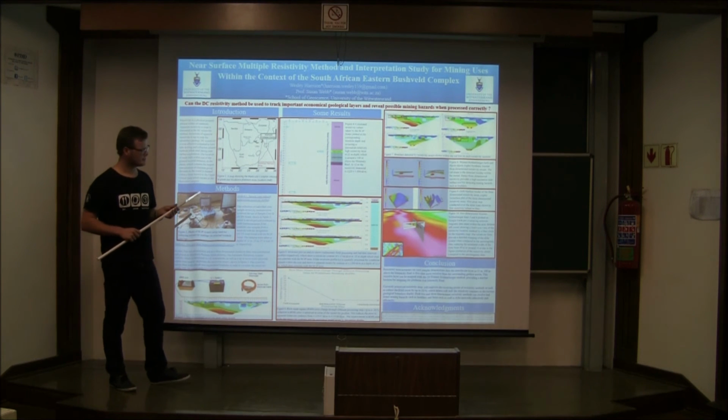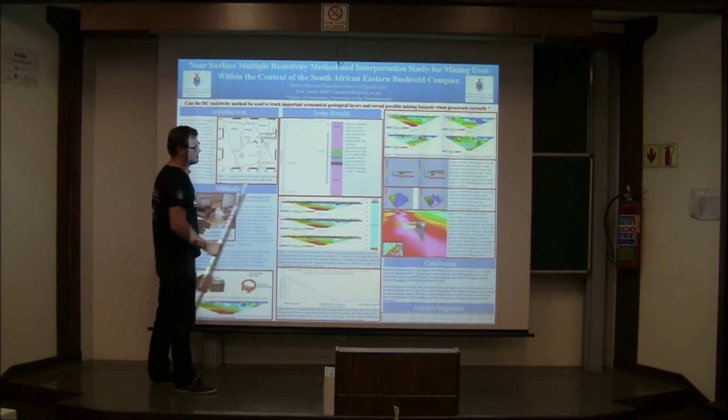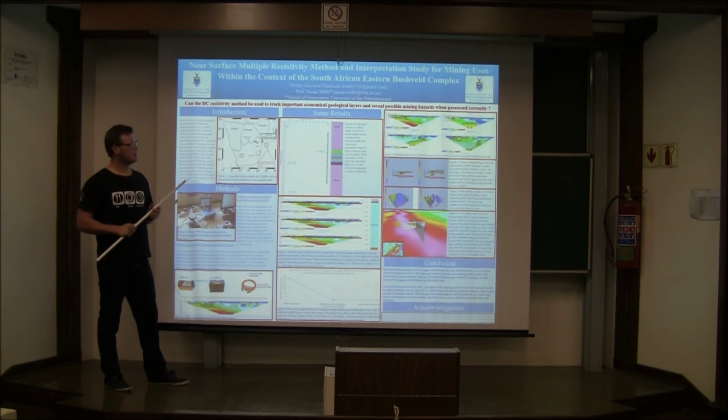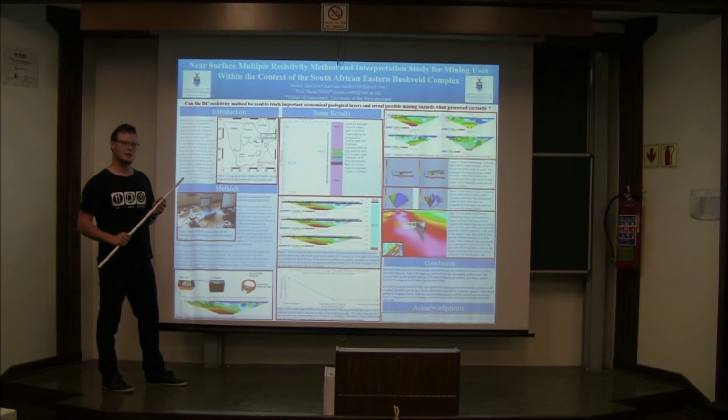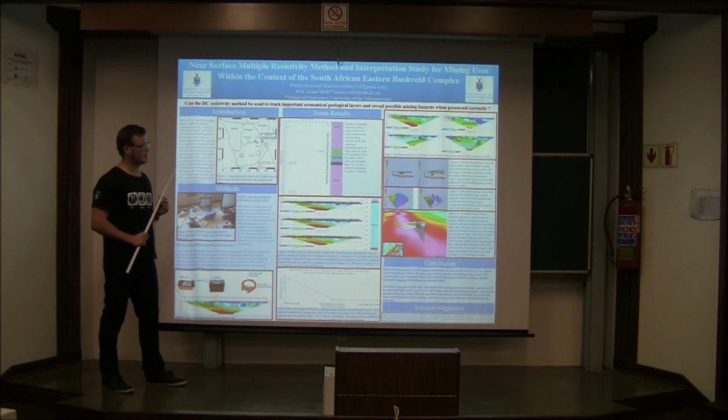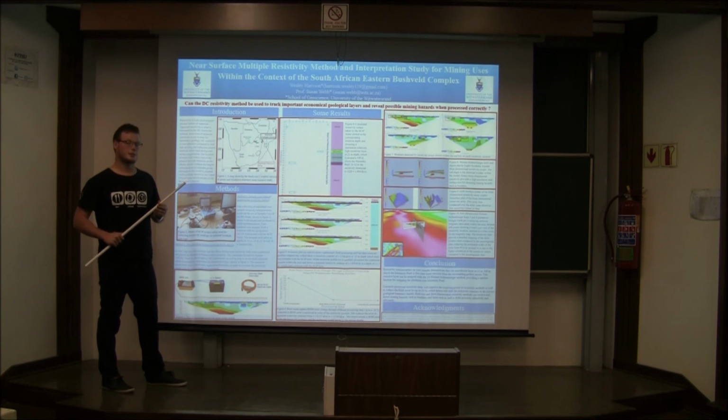the technique itself. Our last two figures, 2 and 3-dimensional resistivity profiles, were constructed over dike swarms detected by aeromagnetic methods. Now, these aeromagnetic methods predicted the width of these dikes to be around 100 meters, but the high resolution ground surveys of the resistivity methods reduced this width to around 60 meters. Now, this again will be used in hazard assessment within the mining context.